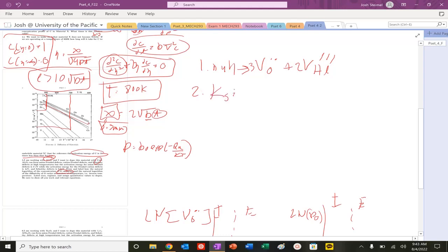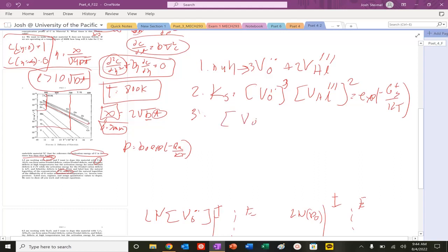Okay, Schottky is equal to, remember I bring out basically the concentration of my products cubed times the concentration of Al squared equals exponential minus G formation of Schottky over KT. That's it. Third, I need to write out my electroneutrality statement. And what was the trick I showed you? You bring out the charge in front. So 2, 3.